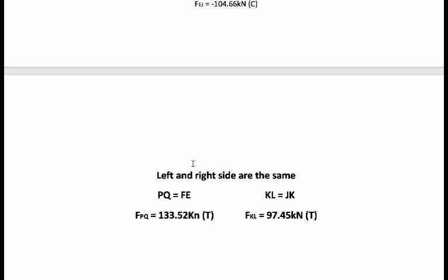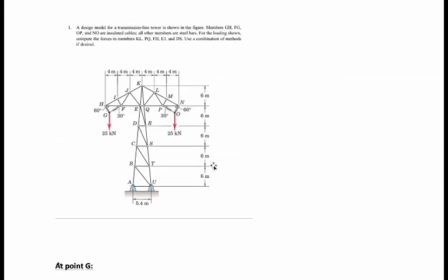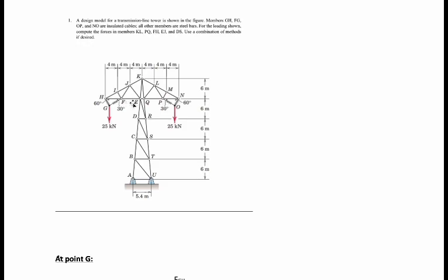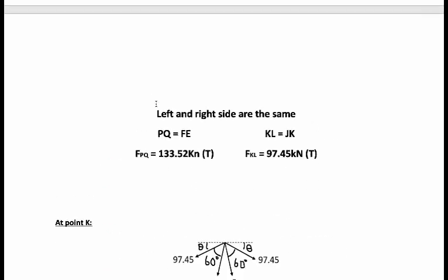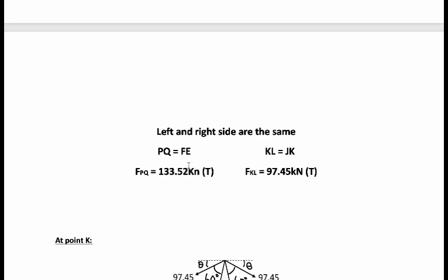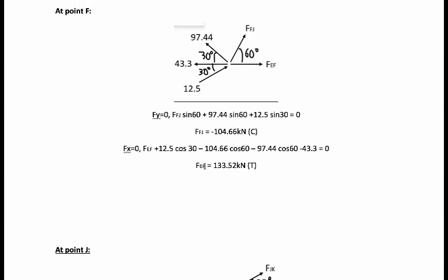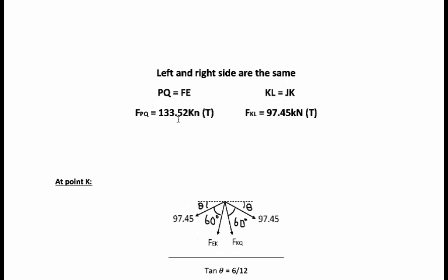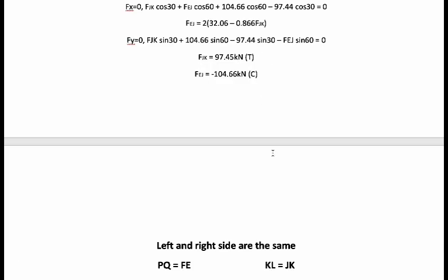So as we can see in the figure above, PQ and FE are equal. PQ here and FE have the same value, so the answer will be the same. For the force in PQ, it's 133.52 kilonewton. So here it's EF. So we got it here. It's tensile.